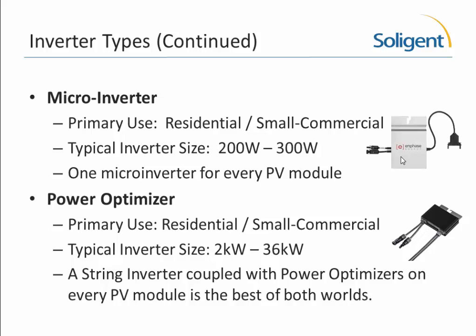The SolarEdge inverter, for example, using power optimizers, works on a fixed 350 volt input. So stringing these inverters is considerably different than with a typical string inverter, say an SMA or Fronius, because they work on a fixed voltage. The thing that varies in the system is the current. So if you had a module in shade, the current output from that module will be lessened, but the voltage coming out of the whole string will still be 350 volts and it'll continue to work. Only one module will be affected. So there's certainly advantages to optimizers with the SolarEdge system.